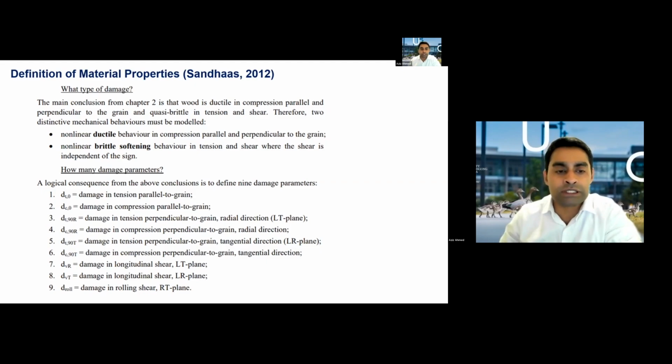I've simulated ductile fracture and shear fracture in steel, where we only need 2 damage parameters, ductile and shear. Whereas in engineered bamboo, we need 9 damage parameters. And Abaqus by default doesn't provide it. You need to create a user-defined field, user-defined material. So we'll see how far we can go within the short time.